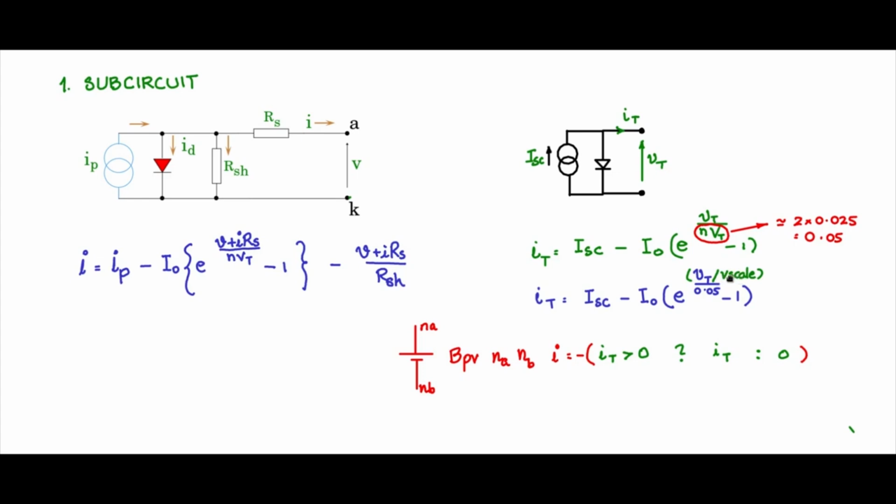If you make V scale any other arbitrary integer or non-integer value greater than 0, Vt will accordingly scale such that this numerator will be around 0.7 to 0.8. So therefore we can get a voltage scaling also by adjusting this value. So V scale and ISC will be the two parameter values that we will adjust.